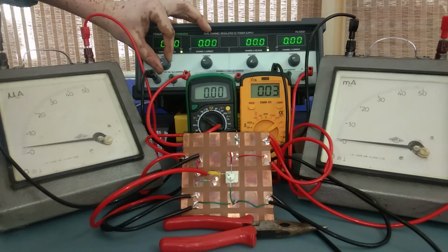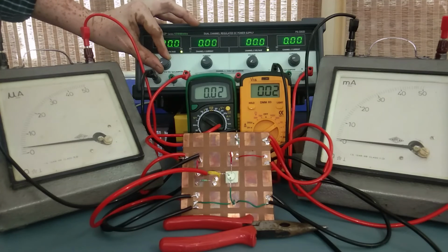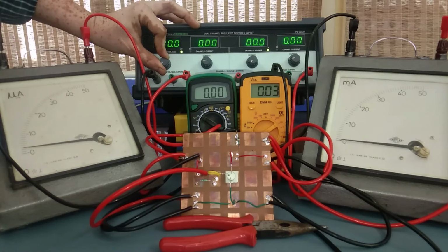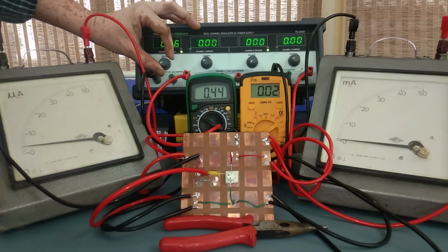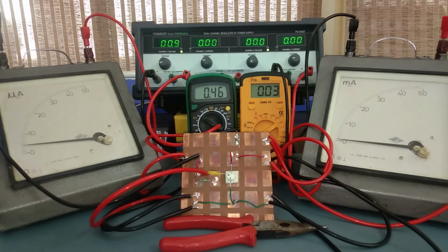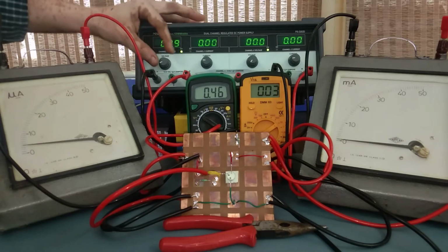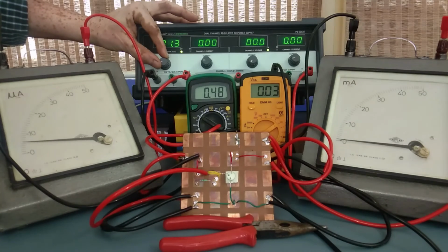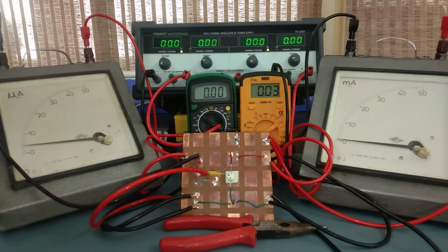You can see here the cut-in voltage. Cut-in voltage is the particular value of VBE where the base current starts increasing. You can see here up to 0.4 volt there is no deflection. Now yes, when you are somewhere around 0.45 volt you can find the initial deflection, and after that there is a gradual increase. Okay, now we will be applying some potential to the collector circuit.